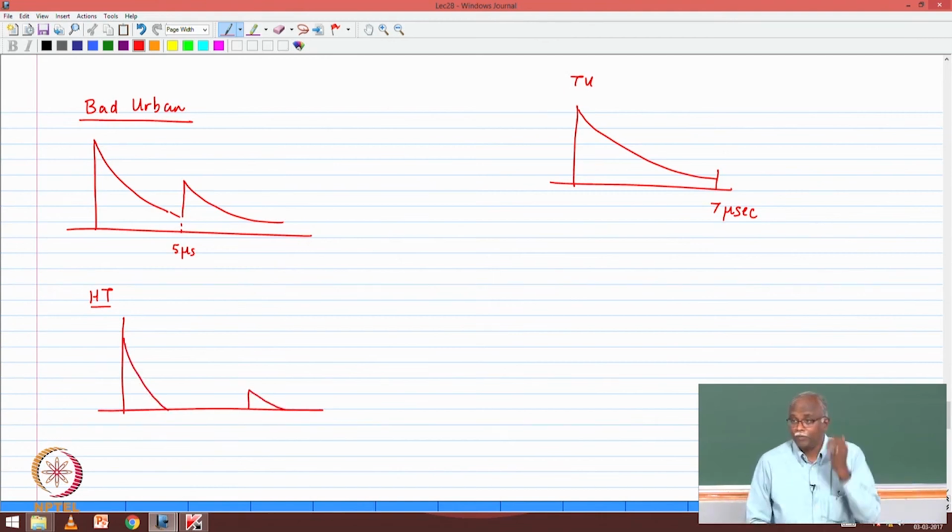No multipath components. Okay, so therefore it dies down very fast, but there may be a hill or something off which the signal reflects, and that can come with a long delay, much longer than you can see in an urban environment. Suddenly, there is a multipath component, not as strong as the original one, but nevertheless a strong multipath component.